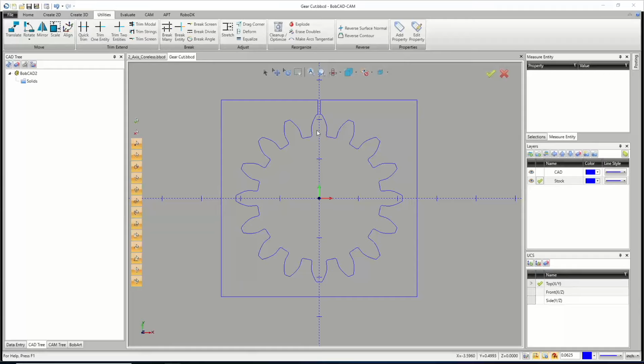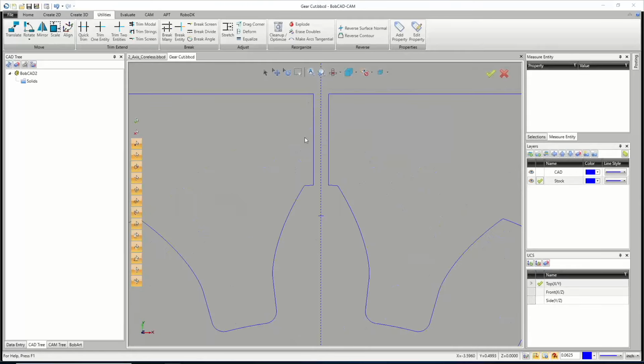So just going to get started and look at some 2-axis open cuts. I seem to do a lot of 2-axis inside, and we're going to do some of that as well. We're going to look at some coreless cuts and everything. But I was looking at a few parts that someone made on GrabCAD, and I kind of like the way they were linking everything together. And it essentially turned all their closed shapes into open shapes. So with this part that we see on the screen right now, I added just this little, it's a 16th inch wide little gap, and we're going to feed in.